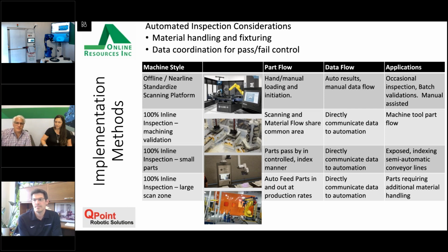Well, you saw when we didn't have the safety right. Yeah, it said safety's not ready. So say get ready. If the go button appears, boom, hit go, you're in auto mode and everything's happening. You don't have to teach them, remember, to jog the robot with the teach pendant back to the safe place before you hit go. Otherwise, when you hit start, the robot's going to swing around and hit a building column and cost 60 grand. Since we have a lot of that motion management and the escape routines built in, the need for training on, oh my gosh, don't break your stuff, is much less required.